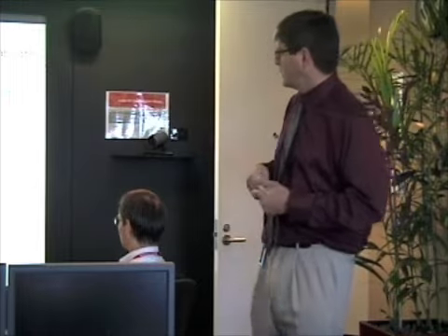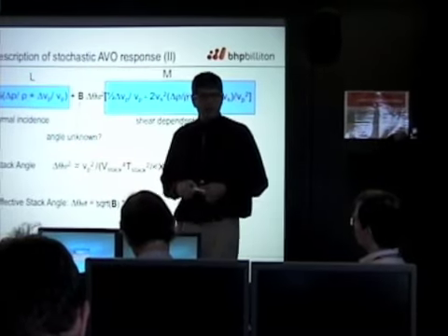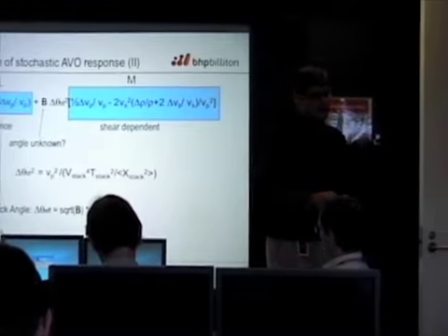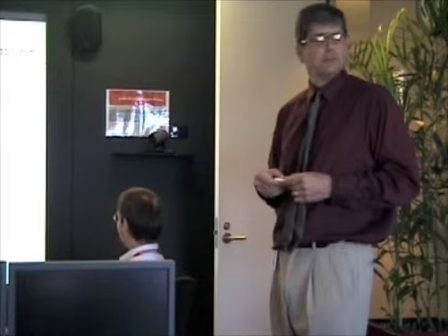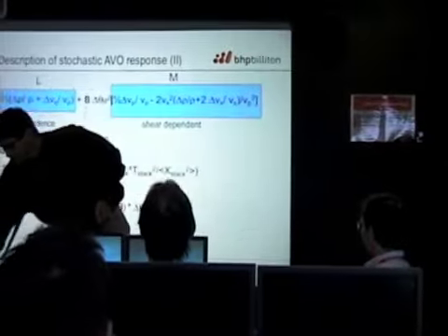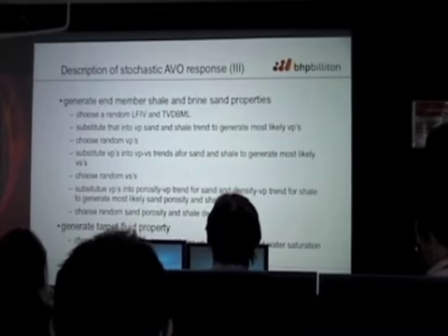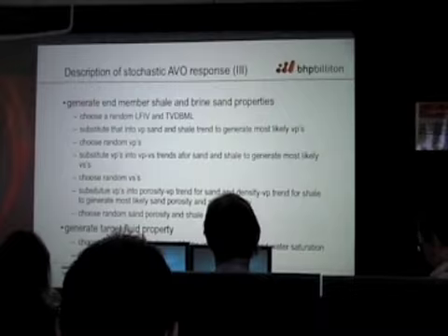Some of the particular large angle behavior on the beginning of some of the hockey sticks can be absorbed by a refit of that slope though too, and that actually can compensate for it. I would say, if you're going to go to anything more complicated than this, go immediately up to a Kennett-like solution, which is a full wave solution and will give you, I think, a better result. And again, there's no reason not to do that.